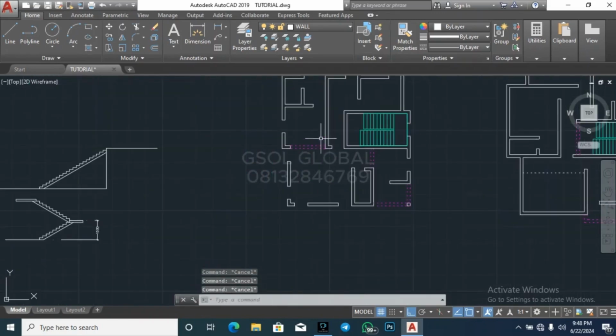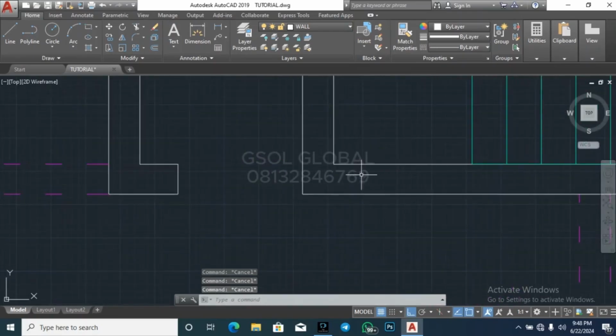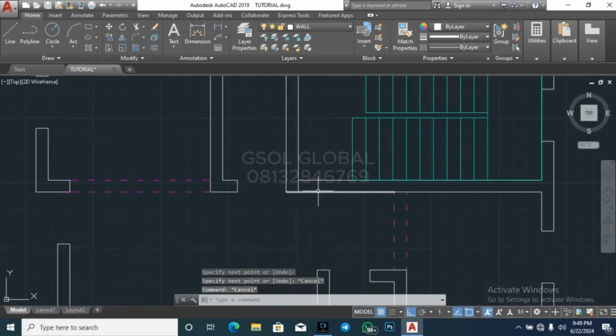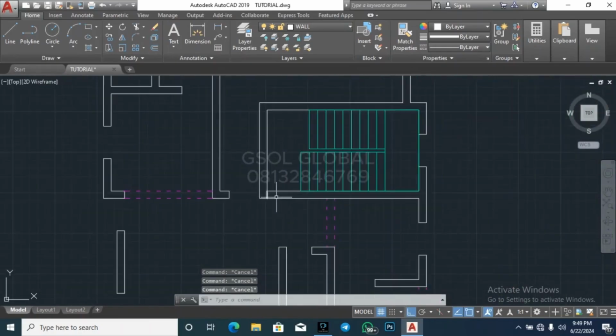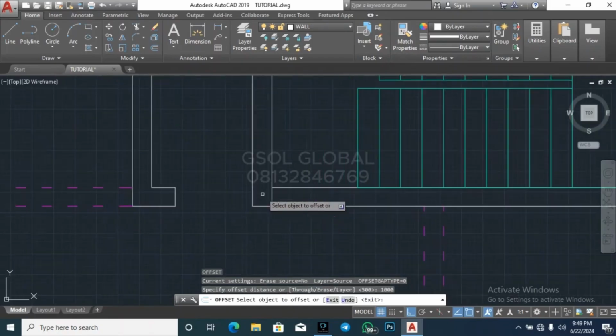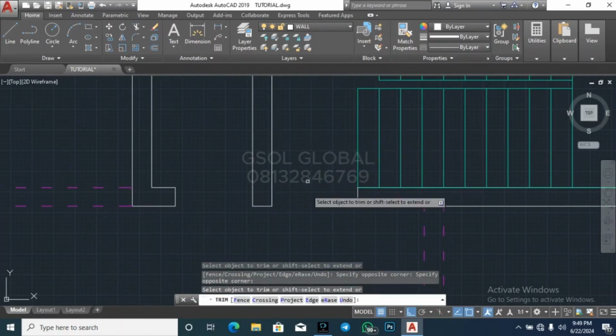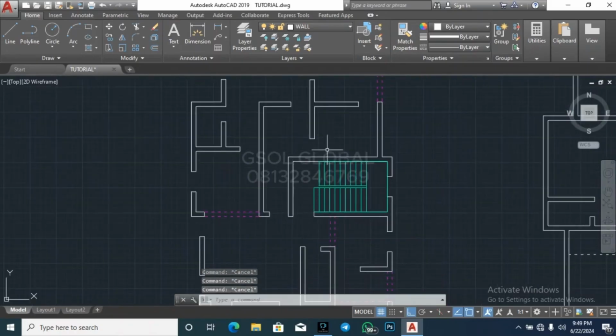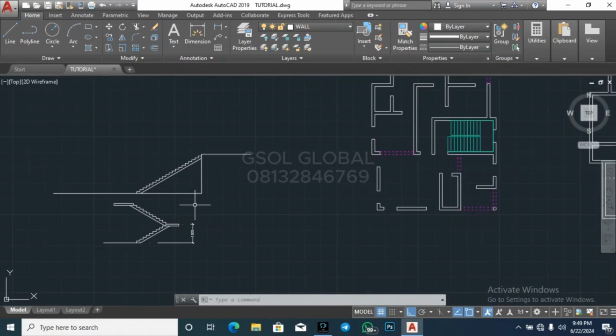All right. So now there's something we'll not do here. I'm just saying it. So let's create our opening. That's our opening for this particular point. So I'm going to make an offset of 1 meter for this opening. It's not a door, just an opening towards the staircase. All right. So our staircase now, this one, if you see it properly, this is the second flight. This one will be above this one. All right. So this is this flight here.